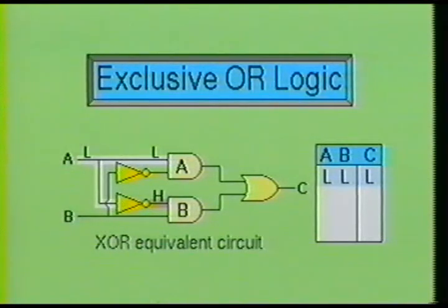This is because the low signal being applied to gate B had to go through an inverter before it reached the input of the gate. We also said that input B was low, so this gives us a low on the other half of gate B and a high on the bottom half of gate A. Remember, the inverter on gate A changed the low to a high before gate A received the signal. We now have a low signal and a high signal being applied at gate A.